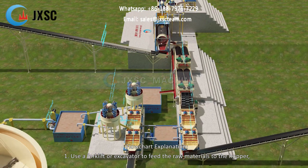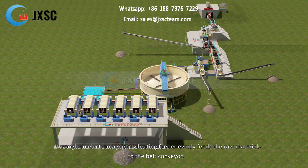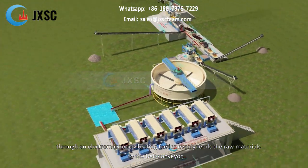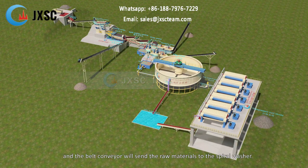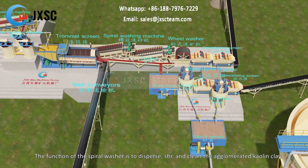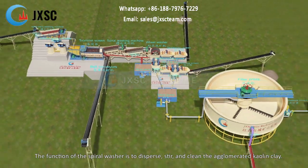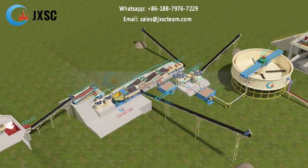1. Use a forklift or excavator to feed the raw materials to the hopper. Through an electromagnetic vibrating feeder evenly feeds the raw materials to the belt conveyor, and the belt conveyor will send the raw materials to the spiral washer. The function of the spiral washer is to disperse, stir, and clean the agglomerated kaolin clay.